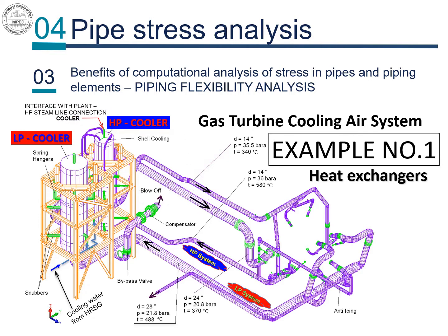This vapor is then used in a steam turbine. The cooled air flowing out of the once-through coolers will hence be used to cool down the blades of the turbine, and it is therefore re-injected to the turbine. As the cooling of the blades on the turbine is very crucial, a too cold gas can definitely damage them, and a too hot gas can fail to cool them sufficiently. The outlet temperature of the air from the once-through cooler is very important, and is the variable that will need to be controlled.